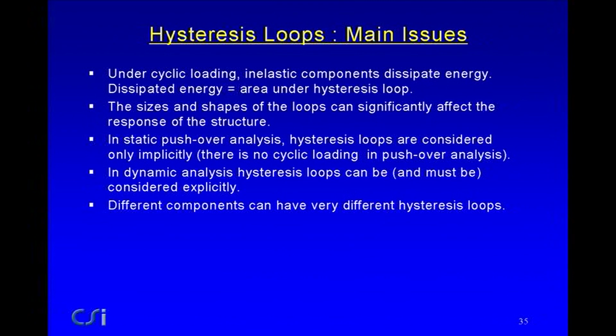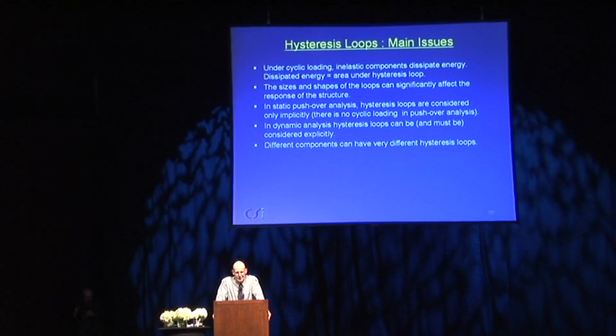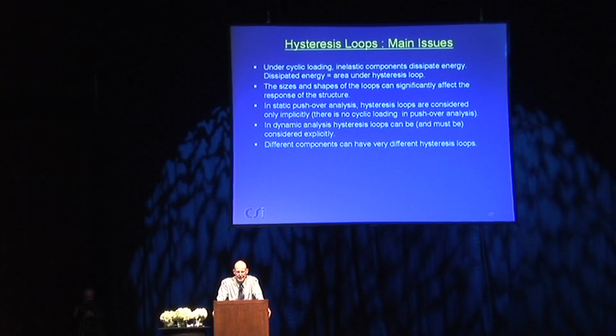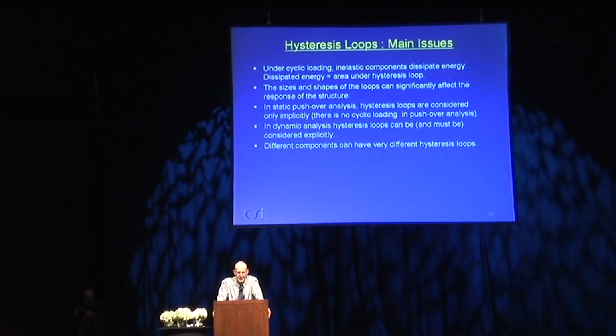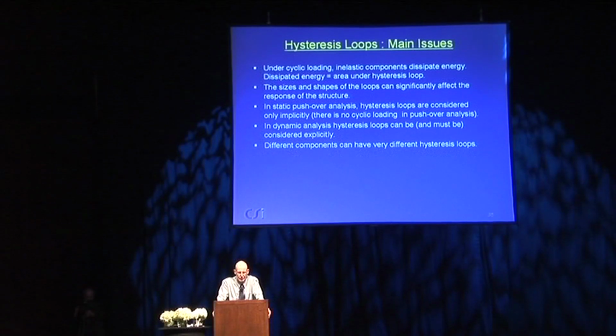Under cyclic loading, the inelastic components dissipate energy, and the dissipated energy is simply the area under the hysteresis loop, or the sum of the areas under all of the loops. And the sizes and the shapes of the loops can significantly affect the response of the structure. The conventional wisdom says if you get into rather long period structures, that the amount of damping shouldn't have very much effect on the result. But that doesn't always seem to be the case. This is a little tricky one. If there is degradation, then I think you should attempt to model it. And within Perform 3D, you can do that. We'll talk about that in a moment.